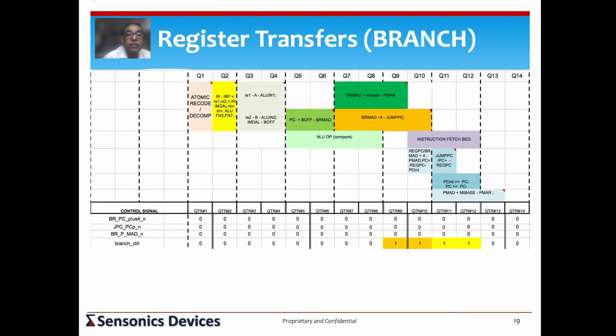This is a branch, again, a little more complicated, because in this particular case, if a branch is not taken, it becomes much more straightforward. And if the branch is taken, what we do in this particular scheme is we compute the branch destination assuming that the branch will be taken, so that the final decision is simply a mux. That way we save a little bit of time in terms of the whole operation.